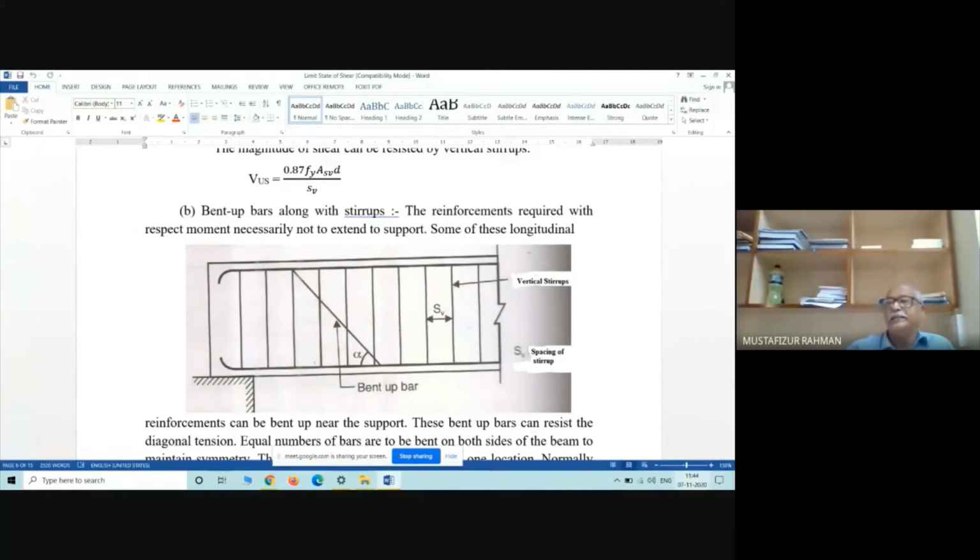So that's why for the reinforcement in the compression zone, the difference between two points should go on reducing. Say from this point to this point it is the length. This is the L. We know the cross-sectional diameter of this, so we can find out R. So we get the L by R value.